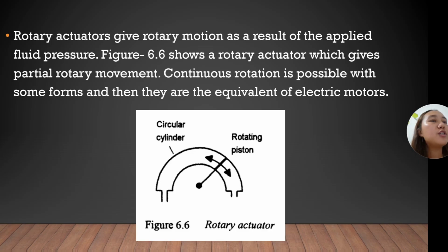For example, if a job requires a 50 kilonewton force and a speed of 12.5 millimeters per second using a 150 millimeter cylinder, we determine two inputs. The required pressure is found from F over A, resulting in 2.8 MPa. The required flow rate is found from speed times area, resulting in 2.2 times 10 raised to the negative 4 cubic meters per second. This highlights that force dictates the pressure requirement and speed dictates the flow rate requirement.